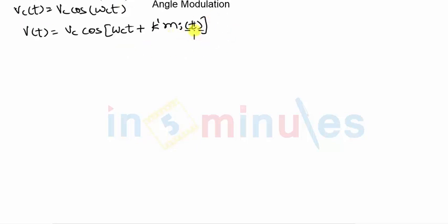I can only understand the nature of the signal if I can define mi(t) that I've taken. So here mi(t) is nothing but, i stands for integration, m(t) is my modulating signal. So mi(t) is nothing but the integration of the modulating signal, m(t). If I integrate m(t), inside the integration I'll use a dummy variable, so it becomes the integral of m(τ) dτ. And mathematically integration is defined starting from minus infinity to any present time instant t.